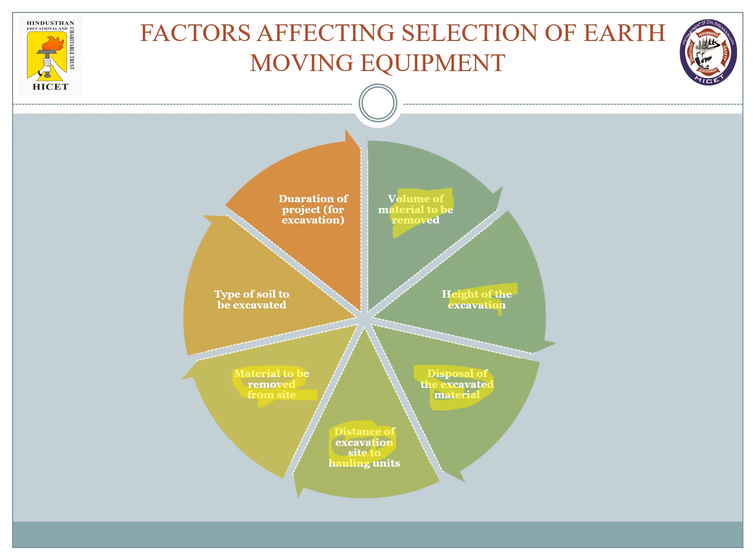And materials to be removed from your site, if they are too heavy, like you have big rock boulders, you have to use different techniques, like blasting can be done to remove all your materials. Then the type of soil to be excavated, if you're having very hard soil like we have seen, instead of rocks, if your soil is too silty or too watery, if you have clay soil, you have to deduce certain methods and use corresponding methods to remove the soil.